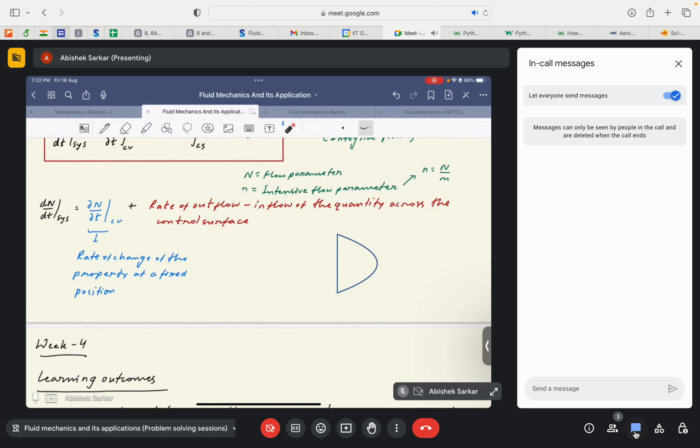Since we are not dealing with that, we are just assuming a uniform velocity, right? Since viscous effects are not considered, at the inlet it will have a uniform velocity, say 3 meters per second. Then this is the value that we have to consider at the inlet, and again at the outlet. But if the tube that you have chosen is itself moving, then the fluid would have a relative velocity with respect to the tube.